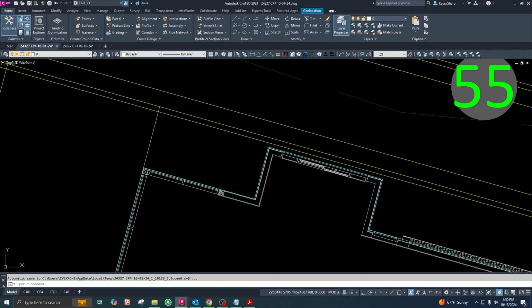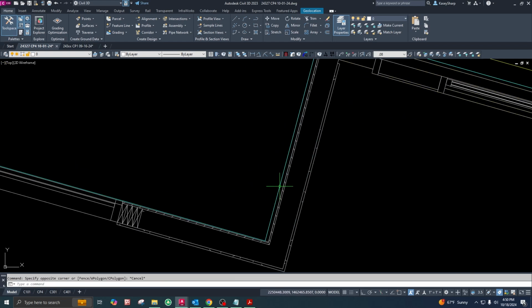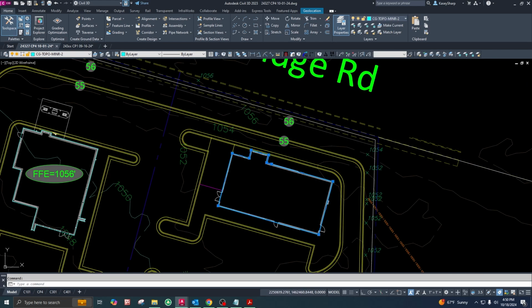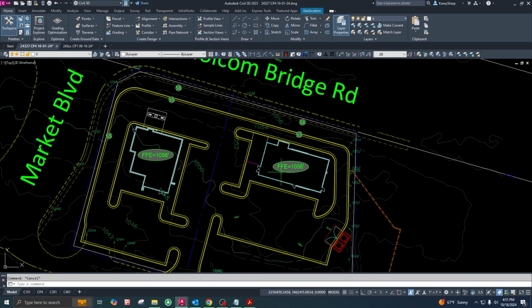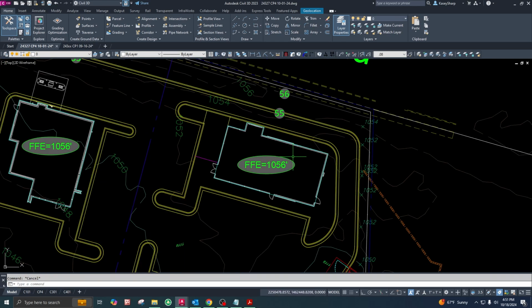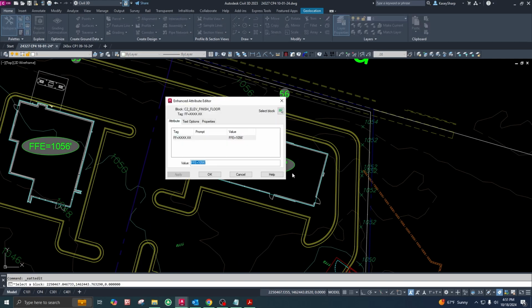Give us a 2% cross slope. And this drive-through should be fine, at least for now. So we'll go ahead and set that at 10, 55.2. This guy's actually higher up than this building, so does that make sense? Yeah. 10, 55.2.